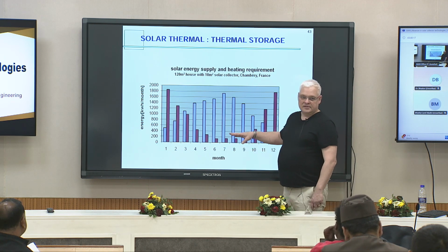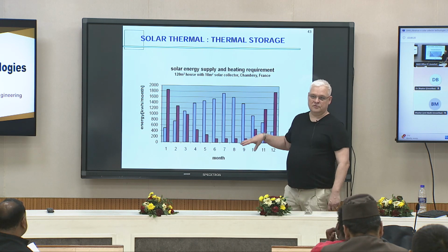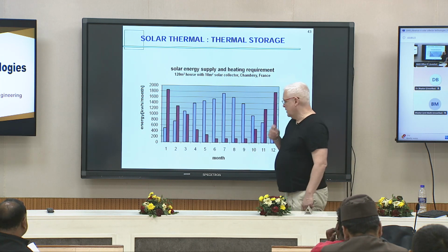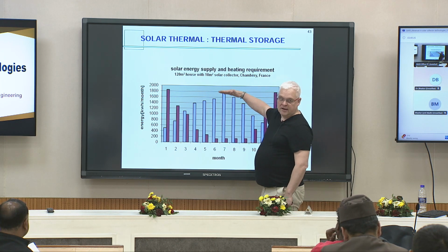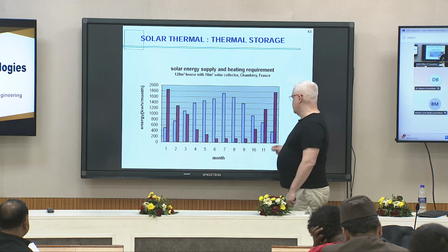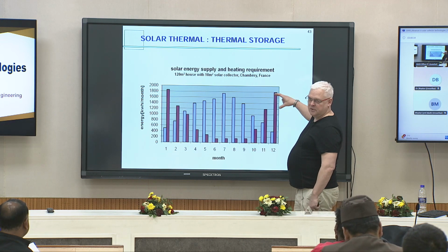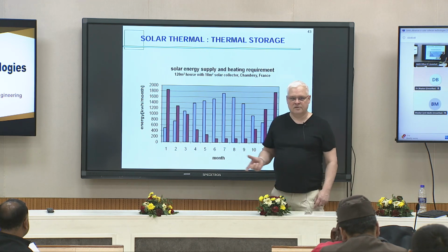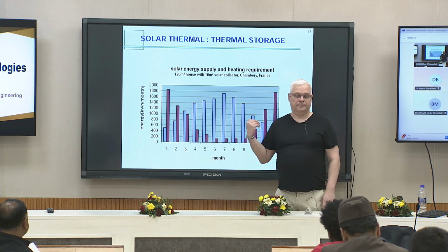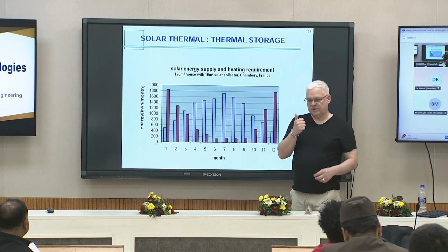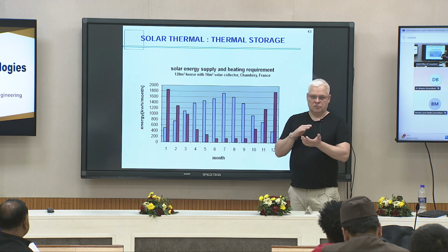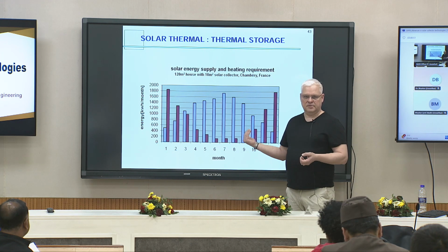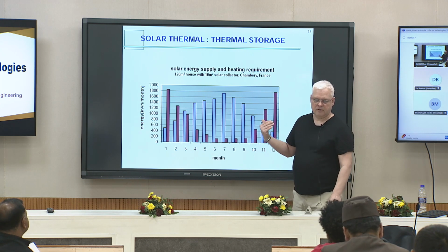But the heating system is out. I don't need to heat my floor. And so I'm producing the maximum in July. Potential is July, but I just need that. Whereas I need a lot here in the winter time, but I can only produce that. Okay, so it is for that the thermal storage is essential, and it could be essential between night and day, between one day to another, but at this scale could be also interseasonal, okay, to long-term thermal storage.